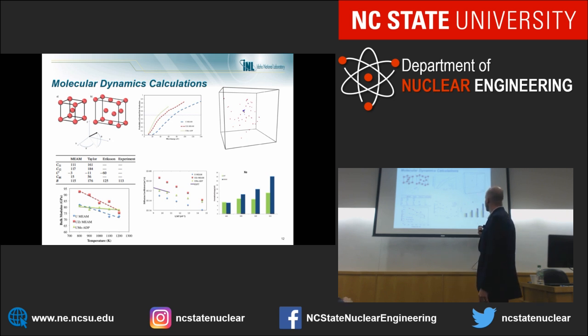So we've taken the interatomic potential, we've done higher energy radiation damage studies as well, analyzing the number of Frenkel pairs made in these systems. And here we're showing a variety of interstitials around a vacancy core, which is a common pattern that you see in radiation damage work.